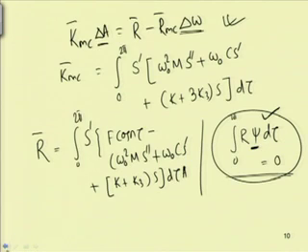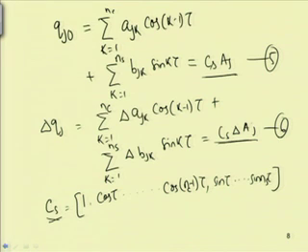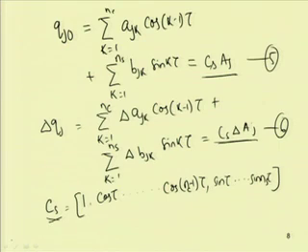So, in case of this incremental harmonic balance method, one follows two steps. In the first step, one takes the state vector and then increments this, and after getting the incremental equation, in this incremental equation one applies this harmonic balance method, using this Galerkin method. So, it reduces to a set of algebraic equations which are solved iteratively by using this Newton-Raphson method. Now, there are many modifications of this incremental harmonic balance method also. So, one such modification is carried out by